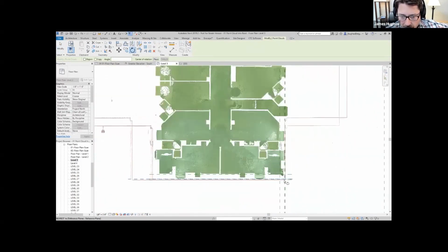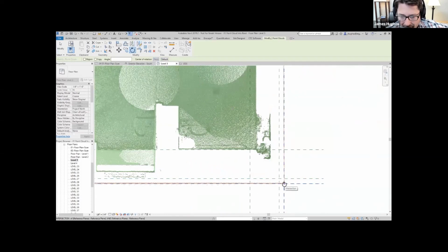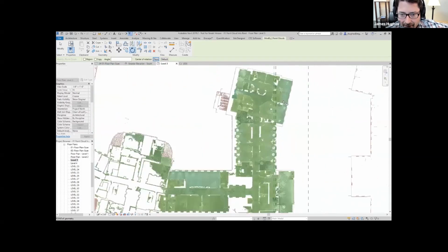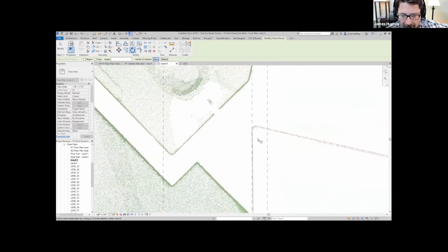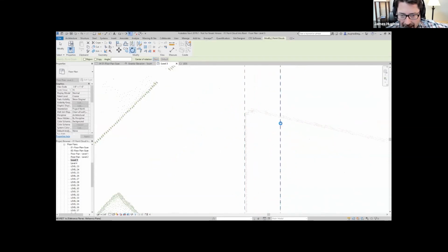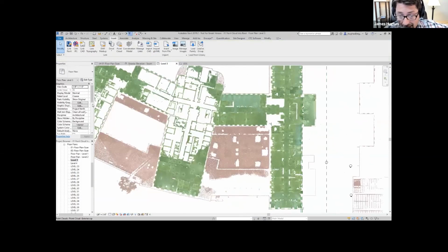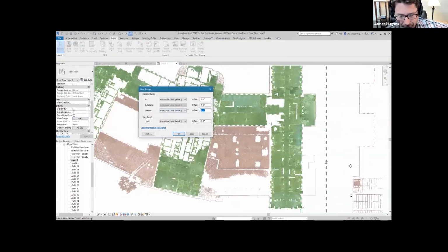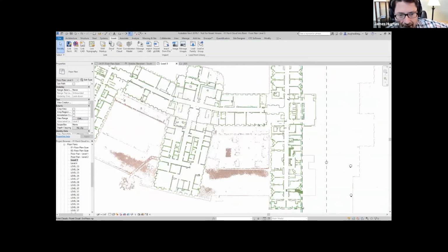And so we'll go to the rotate command. I get a hard snap here exactly at the corner. I can zoom in and find, I mean, within 1/8 of an inch where that edge is, and then rotate it. Along the whole length of the building is now correctly aligned instead of fast and loose aligned with Project North. And this is key right here.